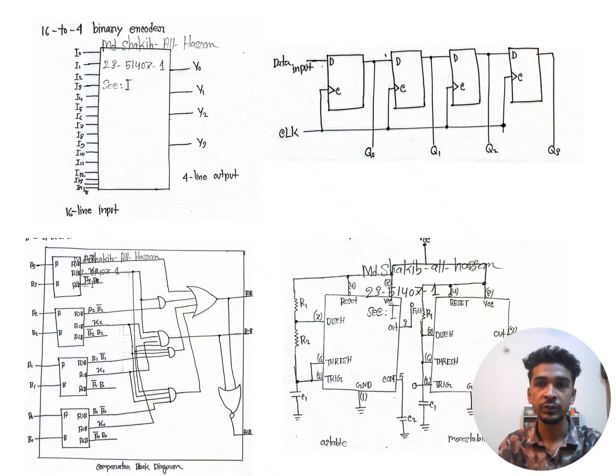Then we use a shift register. By using a SIPO shift register, serial input data is shifted in bit by bit with each clock pulse. After all bits are received, the data becomes available at the parallel output. This makes it easier to process, compare, or display the data.